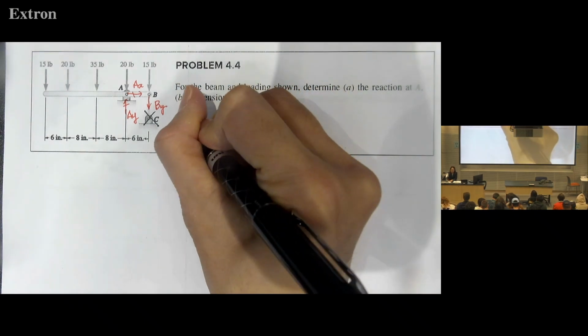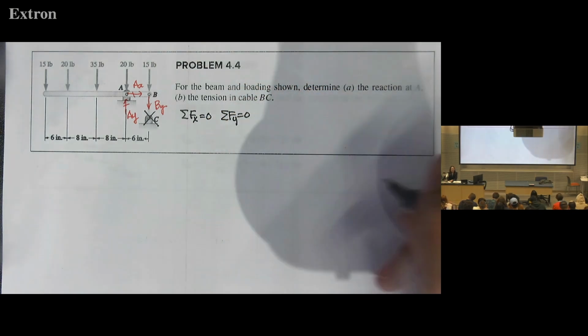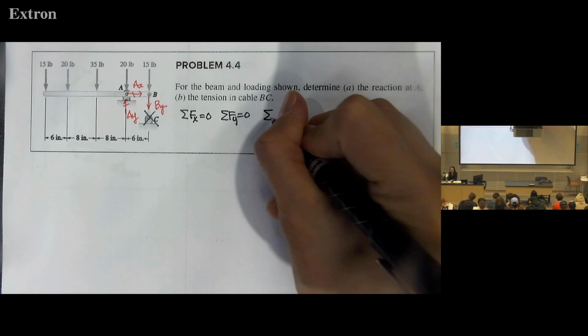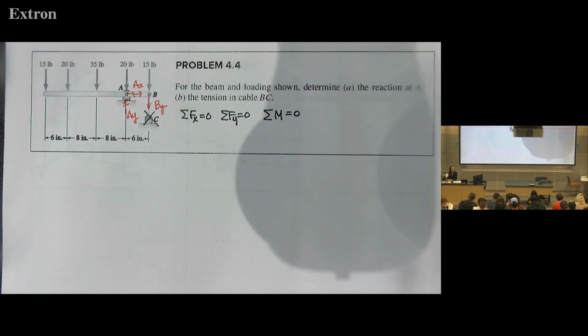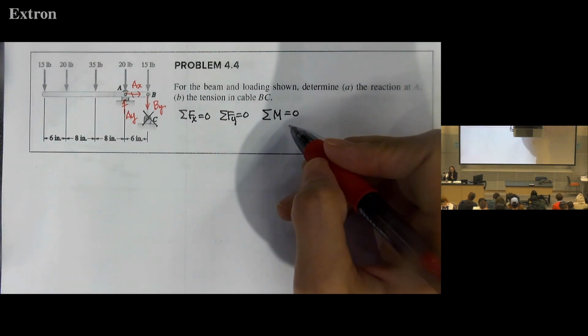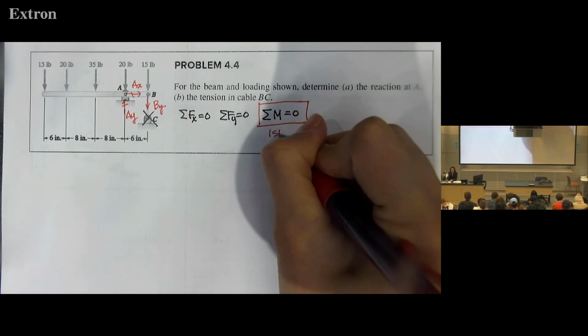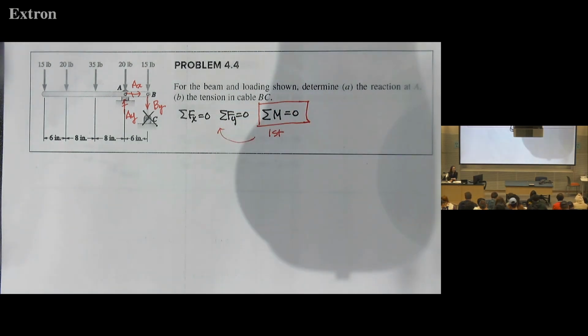And it's 2D equilibrium equation. We have 3 equations, right? So you already know the Fx, Fy equations from midterm 1, and then we are adding the moment equilibrium equation, okay? And then typically for a 2D problem, solve the moment equilibrium equation first, and then solve either the force in x direction or force in y direction equation. And you will see why soon.